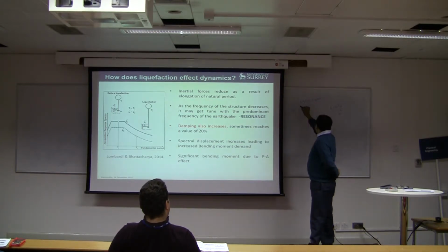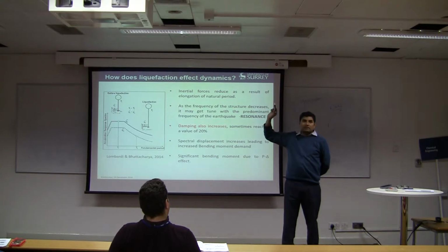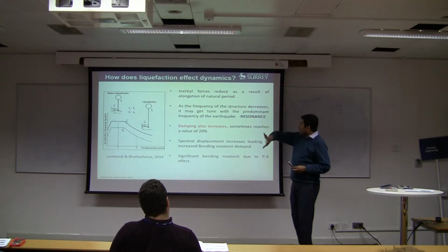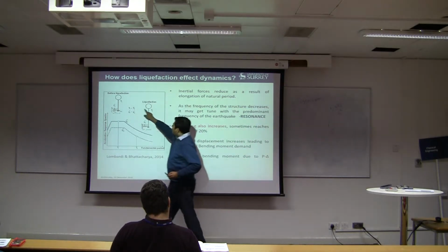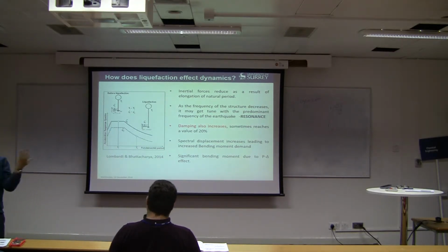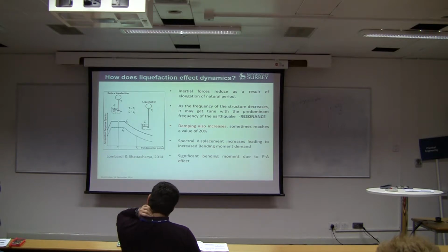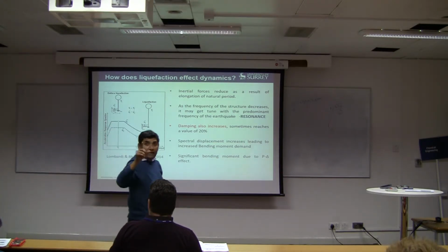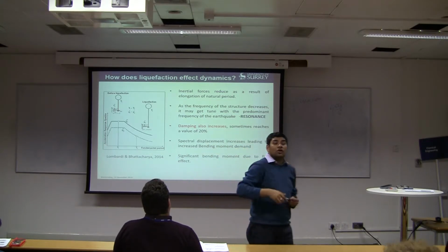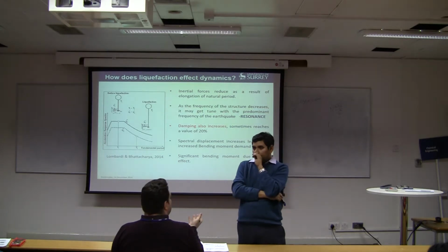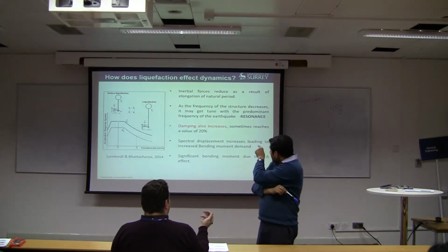So you need the eigenvalue and eigenvector for what reason? To find the frequency. If you see everything we do, we start with T1 and T2, the time periods, and those will show you how to calculate T1 and T2. So the mass matrix, K matrix, and then you did response spectrum, and that will tell you how to get the inertial loads on structures. But the other one here is the frequency of the soil.